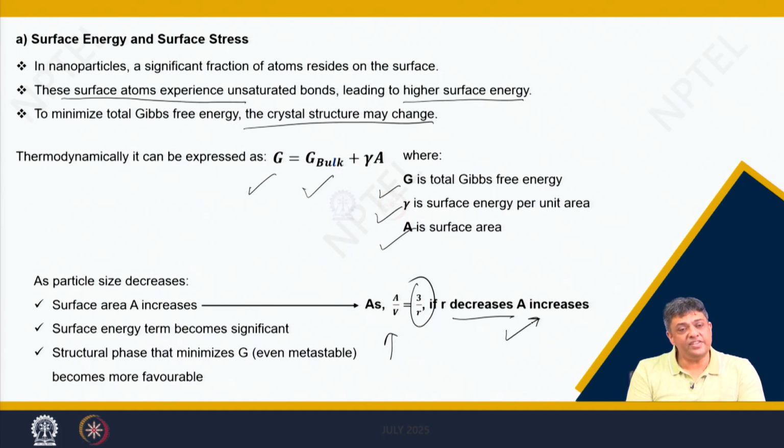So, surface energy terms become significant and a structural phase that has the capacity to minimize this energy, even if it is in a metastable state, becomes more favorable. So, just because surface area is becoming larger, you are forcing the structure to readjust so that it can minimize the energy.